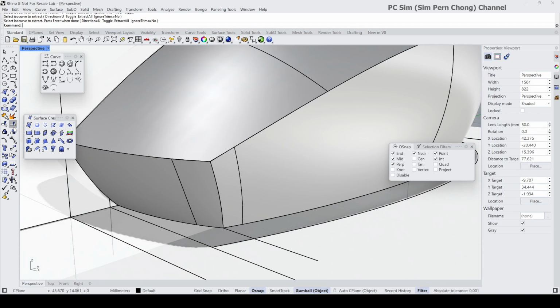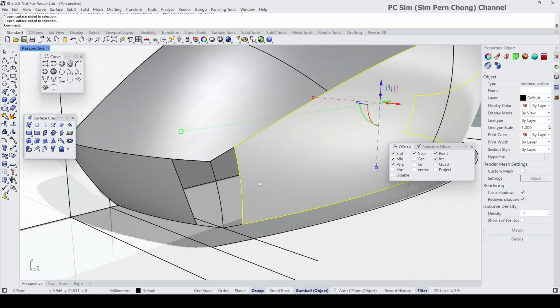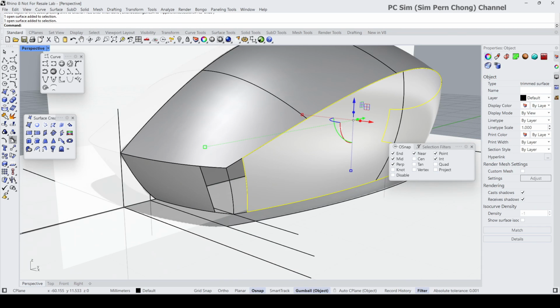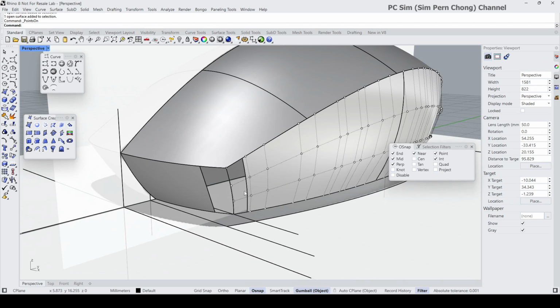And then we can do the trim. Cutting object. Okay, we got something like that. But the control points are coming here, so I guess I want to do nicer, cleaner work. I'm going to use a string trim.